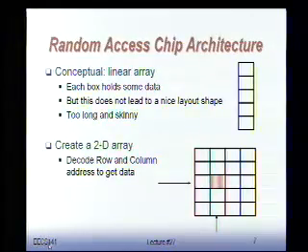Because ultimately, a memory is a very regular structure. Logic is a mess. You've seen this. When you have to lay out your adders and connect the things together, you get these wires all over the place. It's painful. While in memory, you just put rows of cells and rows of cells and rows of cells, very regular, and you put a very nice regular interconnect grid on top of that. So everything is nicely structured. It's very repetitive. So from an analysis perspective, it's a lot easier too, because everything is approximately the same. I analyze one, and I just keep on repeating it over and over again. So it's a very different game.